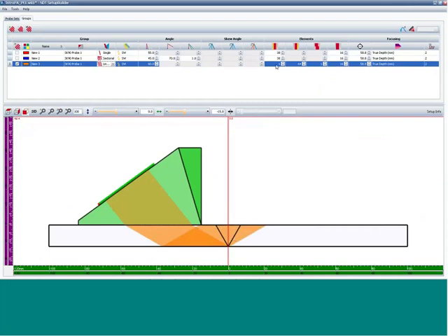This is defined as the element start position, element 1, for the first A-scan. I want to use the entire probe, so I will stop at the last element. I might not need all of that coverage, but I have the ability to use it up until the last 16 elements.